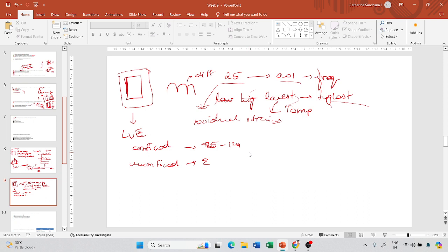Now this is an iterative process, because you do not know the property of the material. You do not know what could be the modulus of the material at a particular temperature and a particular frequency, right? Because the modulus will vary with temperature and it will vary with frequency.